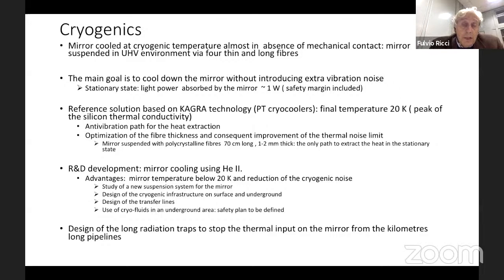The typical problem of the cryocooler is that these are objects which vibrate. So we have to be very careful in trying to screen the vibration that can propagate and spoil the performances of the interferometer, and can spoil the silence in the underground area.